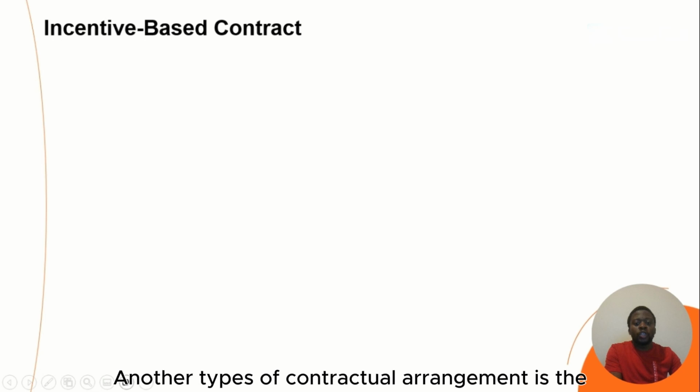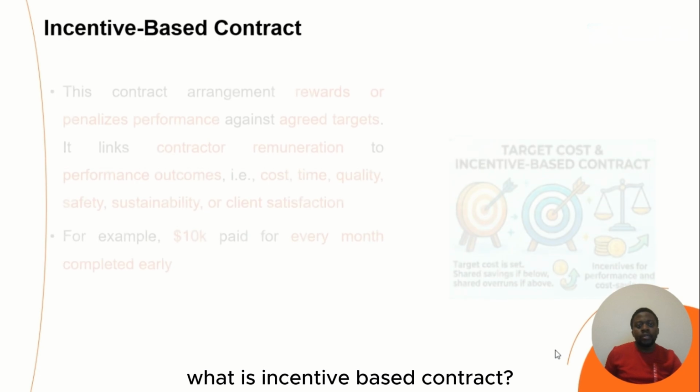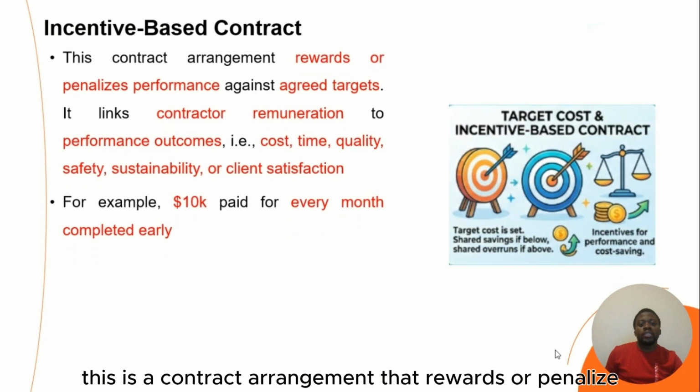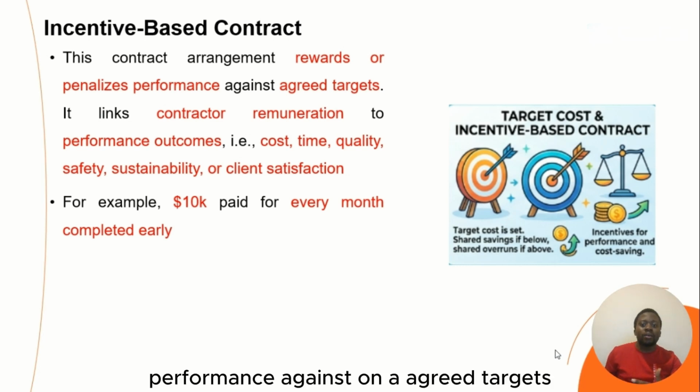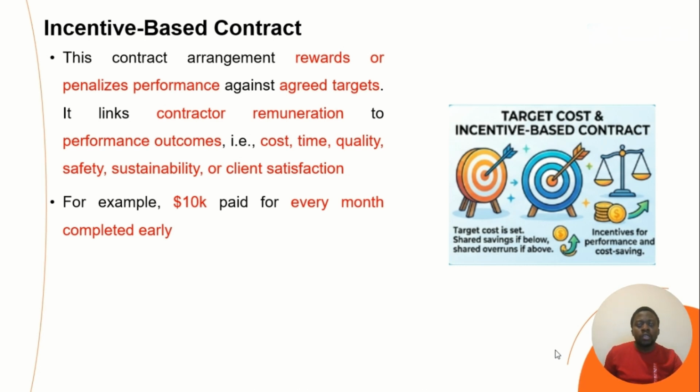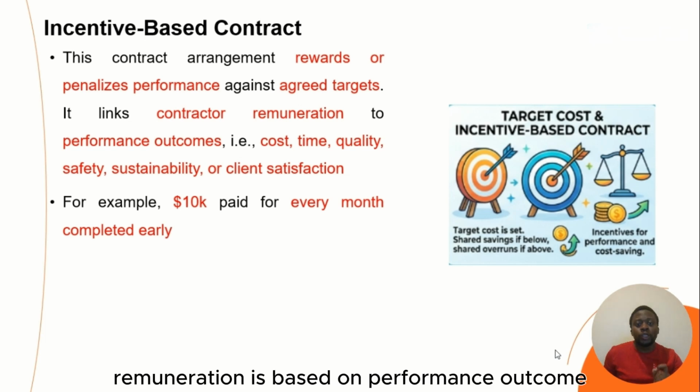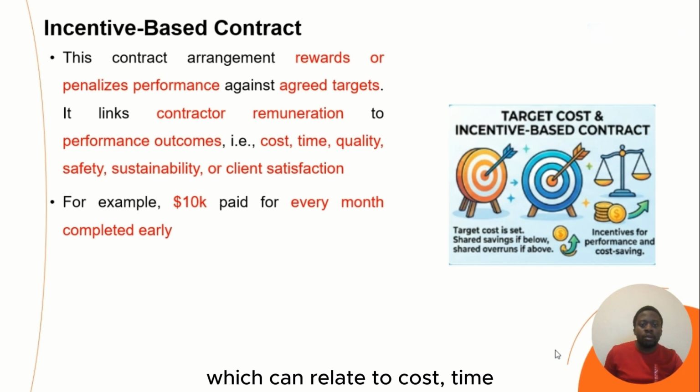Another type of contractual arrangement is the incentive-based contract. What is an incentive-based contract? This is a contract arrangement that rewards or penalizes performance based on agreed targets. So the contractor's remuneration is based on performance outcome, which can relate to cost, time, quality, safety, sustainability, or client satisfaction.